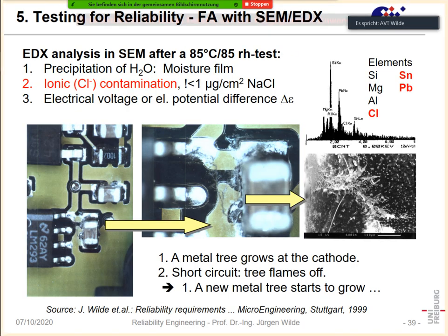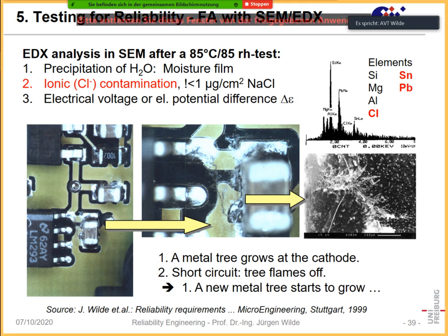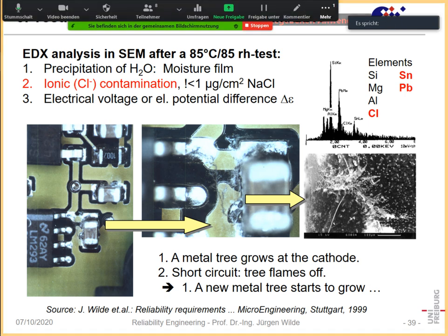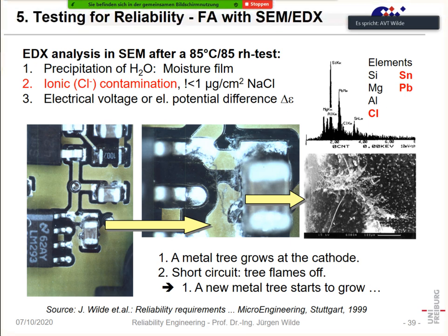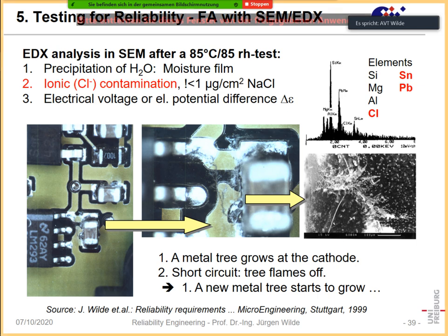Okay, but now let's come back to the more simple things. Here we have an example of just a printed wiring board. A printed wiring board is typically coated with some varnish. Either we just have the solder resist alone, and in that case all of the metal contacts will still be open, because if you would coat them with solder resist, they would not be solderable.